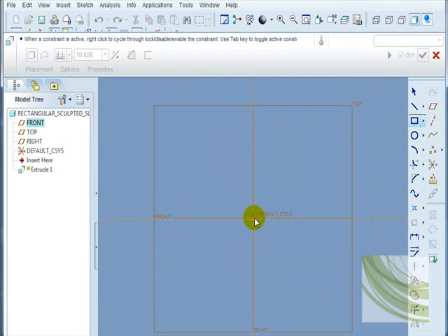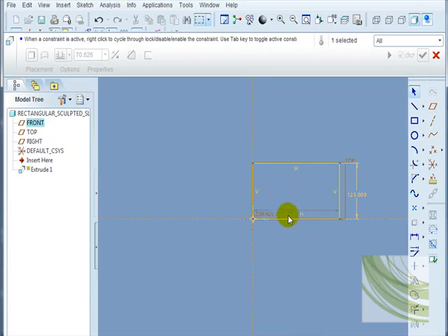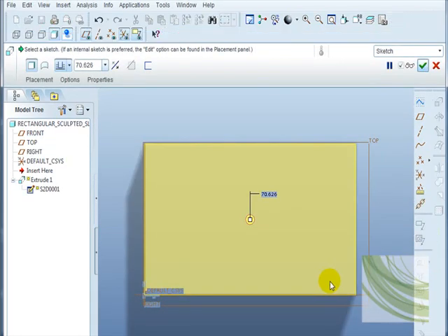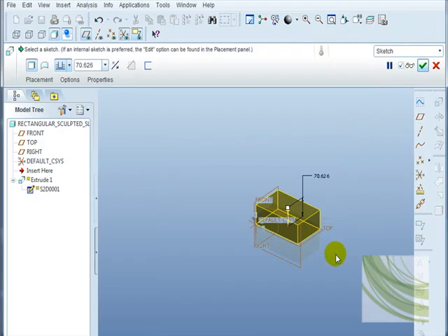Select the rectangular tool, select the shape, left click when I'm ready to do that, go to the selection arrow, select the dimensions. I've already decided to make this 125 wide and 200 long, happy with that. Click OK on there. Again, go to the trimetric view.